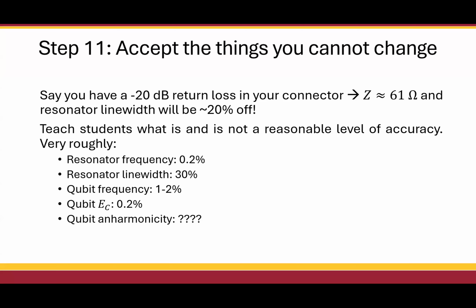Yeah, so it's usable about like 61. You mean not like 61 ohms broadband across like 4 to 8, whatever you're operating in? How much? Well, I would say that if you have a 50 ohm running into a 61 ohm, you'll get minus 20 dB return loss. If you're some number of wavelengths away, depending on exactly how many wavelengths away you are, the impedance you see will range anywhere from 60 to like 40. And that's why you get this variability.